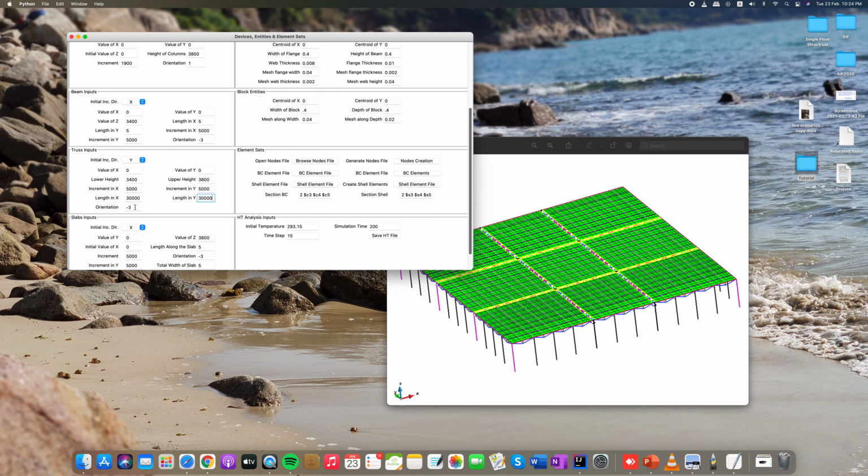And as I say, the orientation of FDS devices is in the Z direction, so my FDS device would be in inverted direction. The temperature is taken from below, so I will give -3. If it is going up, it will be +3. So here -3.